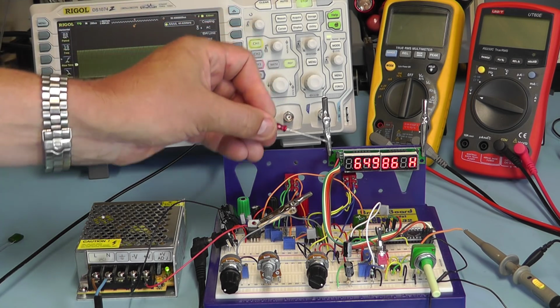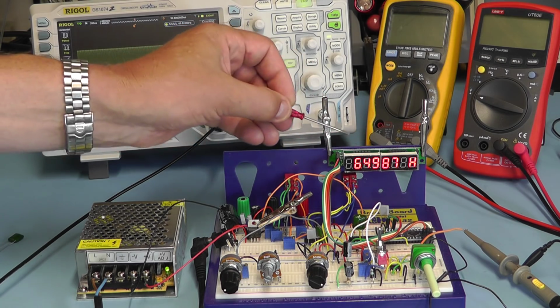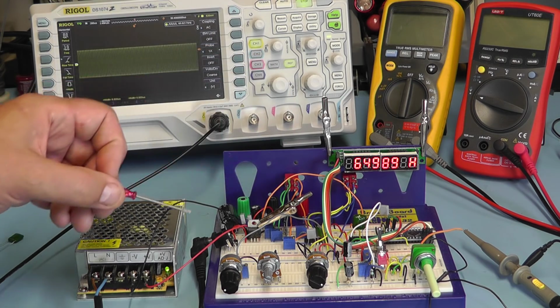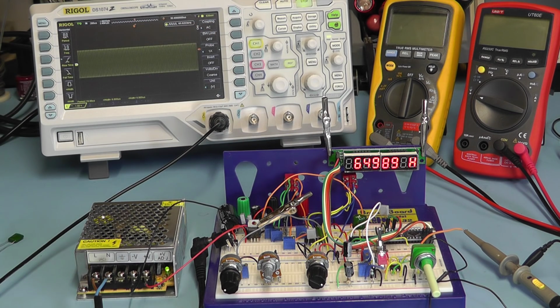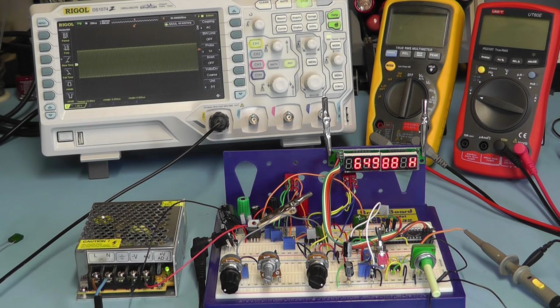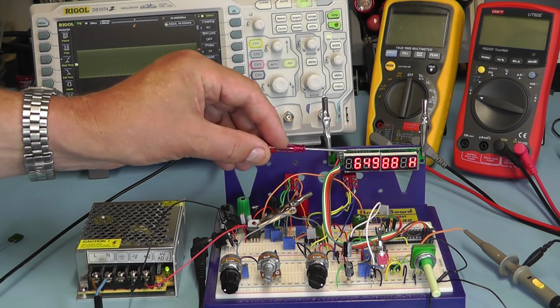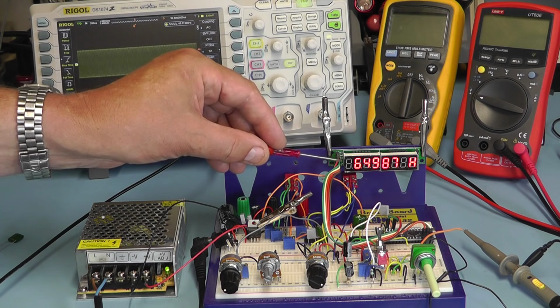Now you'll notice that we have a slight delay on the frequency indication there, and that's due to the timing, the gating signal that I've used in the software. I have a 1 second I think signal to monitor the frequency. We could play around with that, see if we could improve that, but this seems to work reliably, and you just get a little bit of delay from having set in the frequency to the display giving you the frequency indication there.